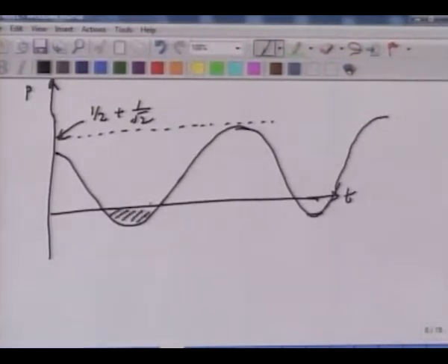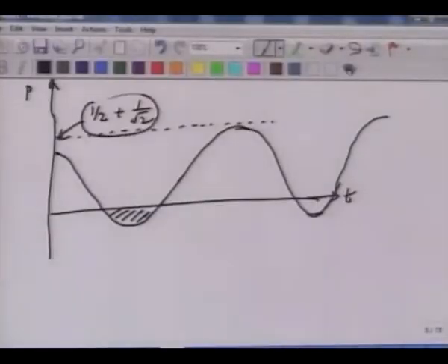So in certain parts of the cycle, energy is getting stored into the system, and in other parts, energy gets dumped back into the system. But the average power dissipated does not change from a purely resistive circuit, which is half a watt, even though the peak power does shift, and it does exceed 1 watt because of this number.